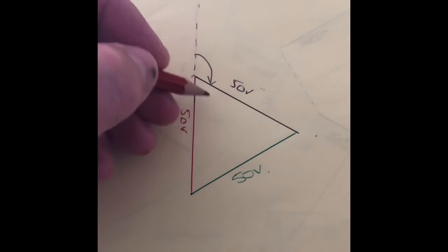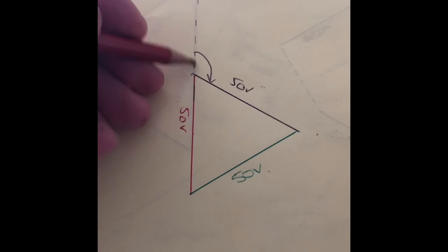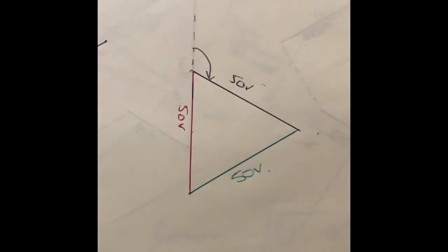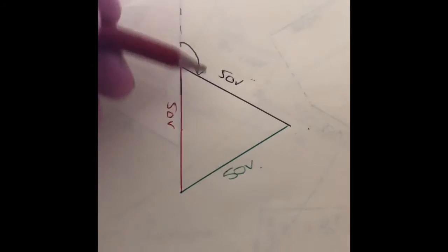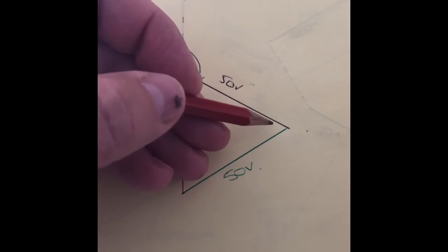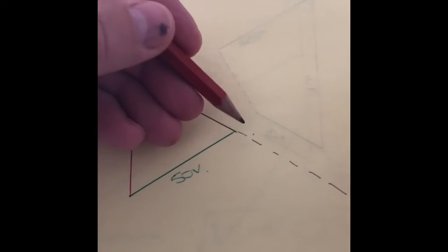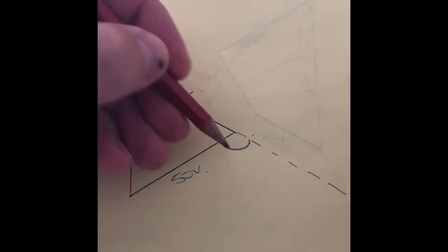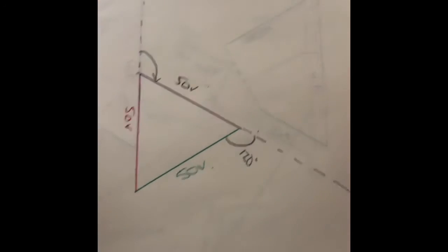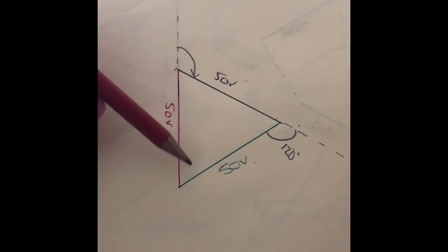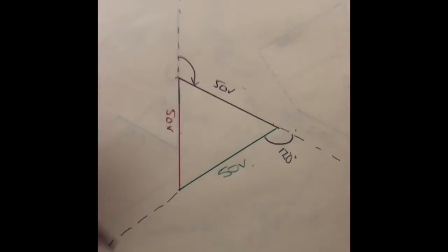Again, we did talk in one of the sessions where we said, why don't you just do the 60 degrees? You can do, but the purpose was to show that we'd extend this line. We would take our 120 degrees and then redraw our second phase, and again I've scaled this down to 5 centimeters. What you would then do is draw your 5 centimeters, but extend this line to show that our 120 degrees is now offset again. And then I would redraw to scale my phase 3, again at 5 centimeters representing 50 volts.